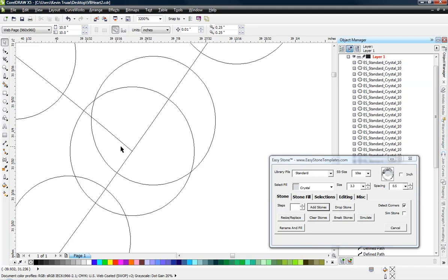But if we understand the tools in CorelDRAW and why things are happening the way they're happening, fixing it is very, very simple. Now we wouldn't want to do it for every single intersection in every single design we do. That's why we have that intersection button. But when it doesn't get it perfect, I'll show you how to fix it. So we're going to go to our shape tool and find out what's really happening here. So with this outline, if I click on that outline of my heart, what's really happening here? Do you see that line kind of turns like a dotted line?